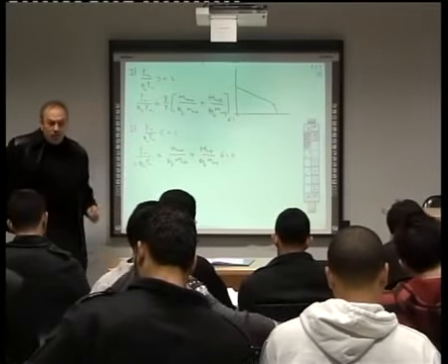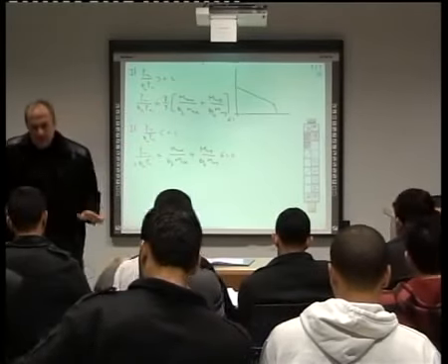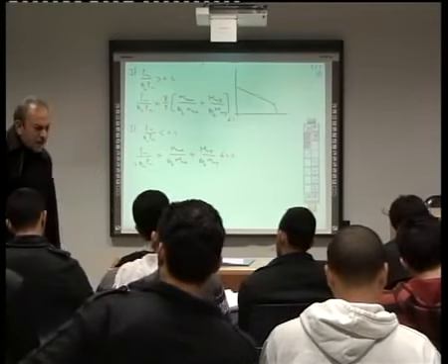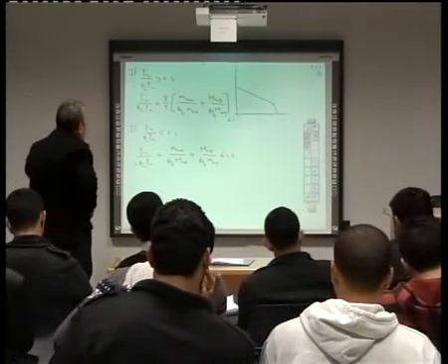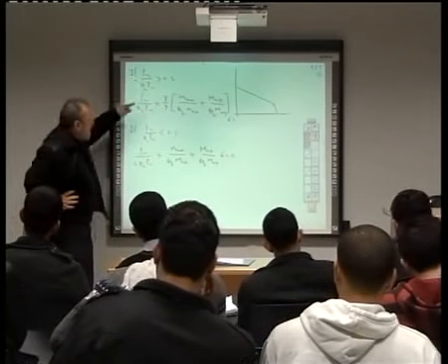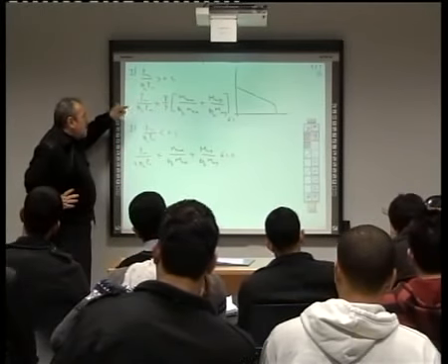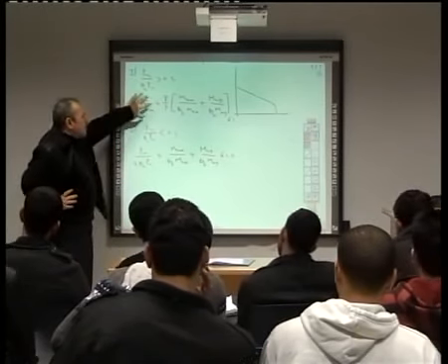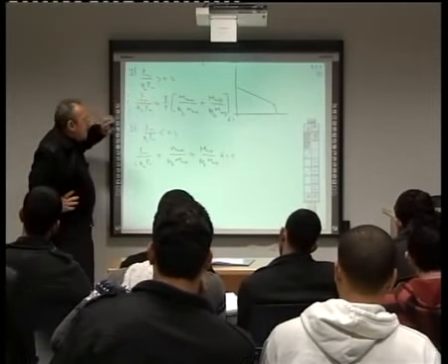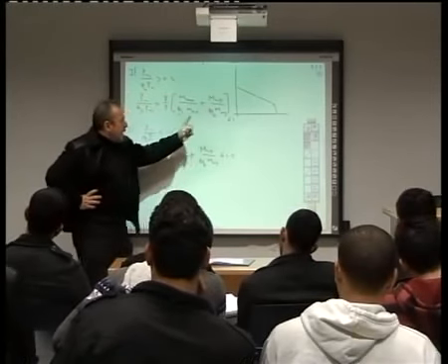My advice to you, for sure you will have a beam column in the final. Now my advice to you is you start dealing with it as a compression member, and then write this equation. Once this equation is written, this term is already calculated. Now we are left with these terms.